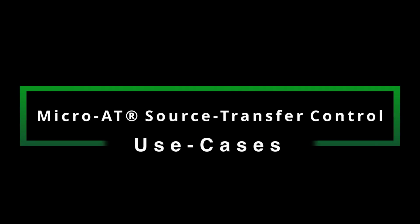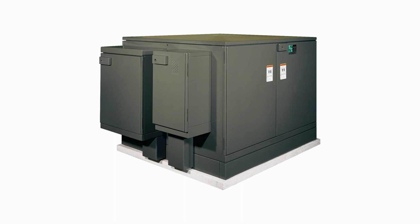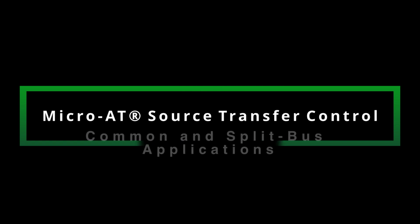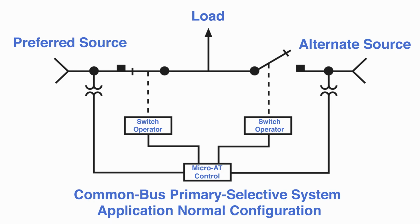This control is designed for use in S&C metal-enclosed switchgear, Source-Transfer Pad-Mounted Gear, and Source-Transfer Vista underground distribution switchgear. The Micro-AT control can be used in common bus and split bus primary selective system applications. In a common bus system, the preferred source interrupter switch is closed and the alternate source interrupter switch is open.